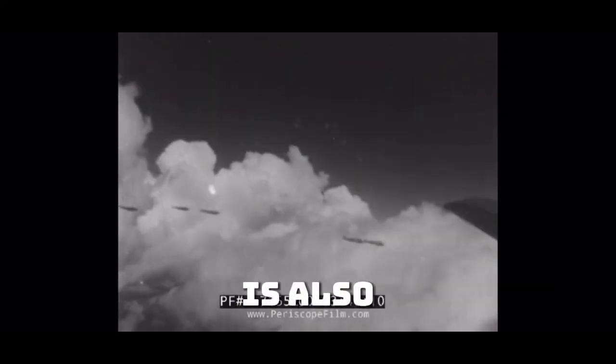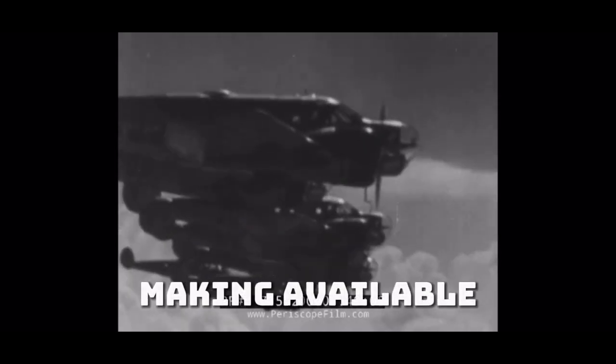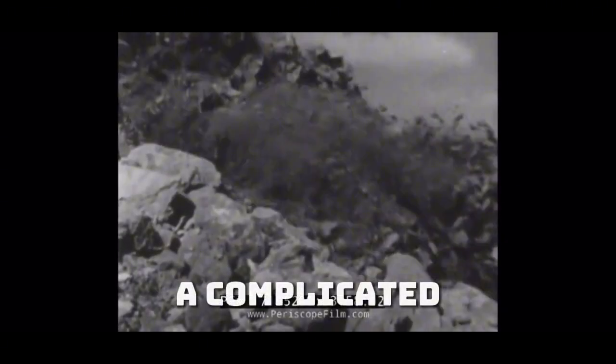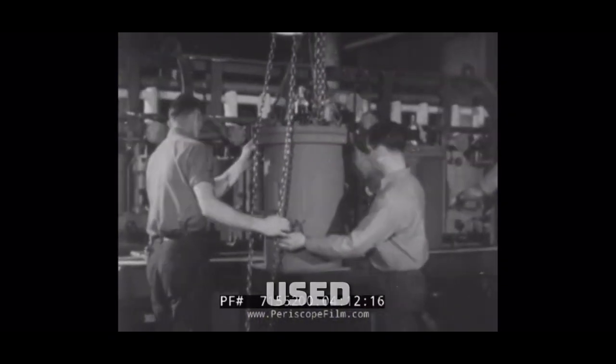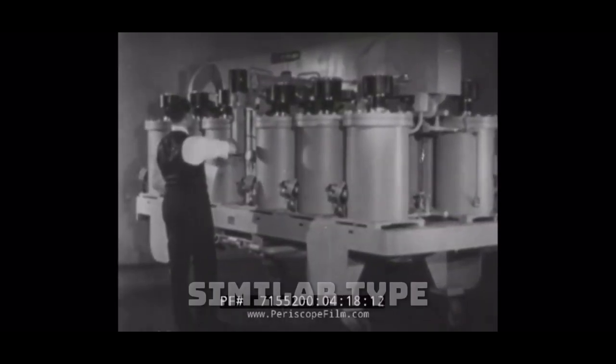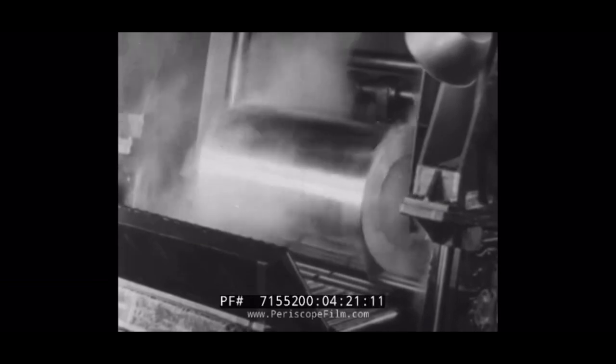Electronic rectification is also helping to build American air power by making available record-breaking quantities of aluminum for plane construction. From Arkansas mud to American air power involves a complicated conversion of materials. Before pure aluminum can be extracted from this bauxite ore, direct current must be applied in a vital reduction process. To obtain that direct current from AC transmission lines, the ignitron rectifier is used. This Westinghouse electronic device converts vast quantities of AC to DC with higher efficiency than similar type of conversion equipment. Today, it's a source of current supply for the nation's great aluminum industry that has achieved a miraculous expansion to meet the demands of a world at war.